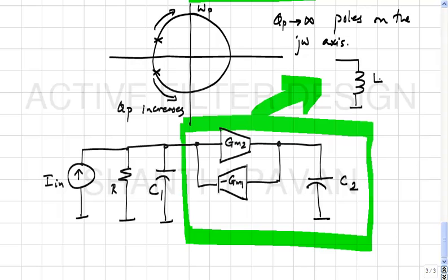So, now you have a network which, as you can see, has got only control sources, capacitors and resistors. Presumably, the control sources can be made with transistors. So, the control sources can be very, very small and compact, and therefore, you can integrate the whole thing on a chip, and you have gotten rid of inductors completely. Okay. So, this must be, what is this voltage?